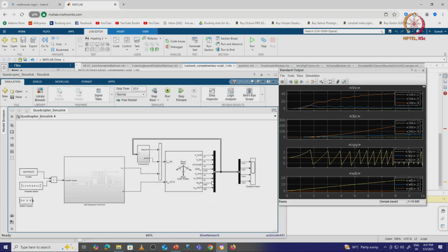In the subsequent lecture, we will talk about sensors. There are important sensors required for control and navigation: the IMU, the inertial measurement unit. You may need a height sensor, which could be a single point LiDAR, a radar sensor, or a pitot tube. You can measure the IMU, which will give you your orientation and acceleration. So, you will have a 6 axis or 9 axis; 9 axis means it will also have a magnetometer. That is an internal sensor which I need. These sensors are required for controlling the aircraft.